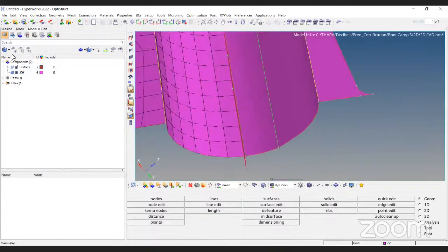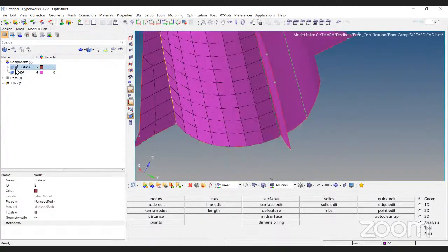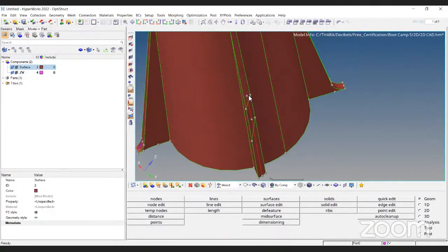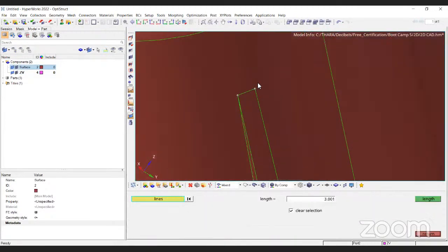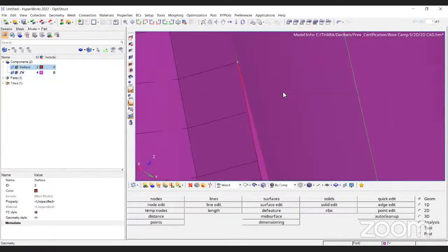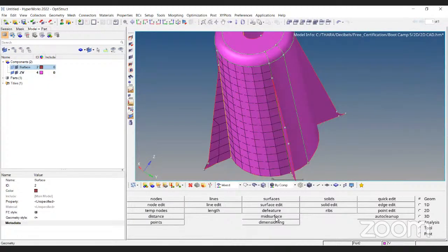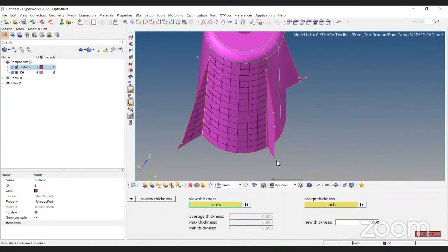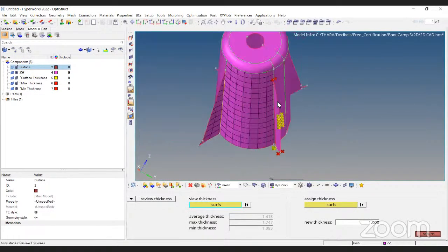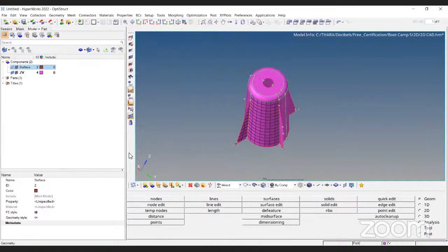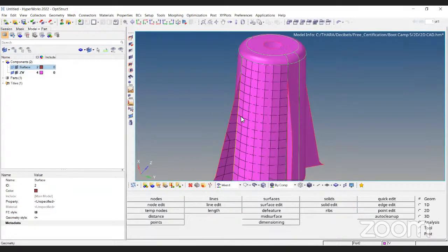But it is not the same as per this rib. You can see manually, and you can tell me, okay, this rib is having a different thickness. So what is the thickness of this rib? Either you can go by choosing like this. Here it is showing 1.8, or directly switch on only the mid surface, go for mid surface again, review the thickness. See, here it is showing 1.4. That is the variable thickness. For this component, it is having a variable thickness.